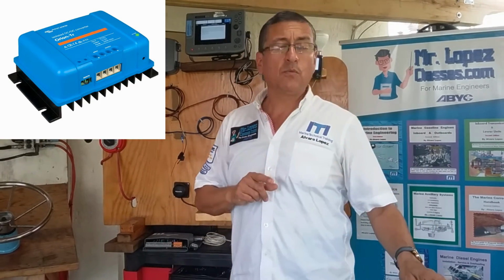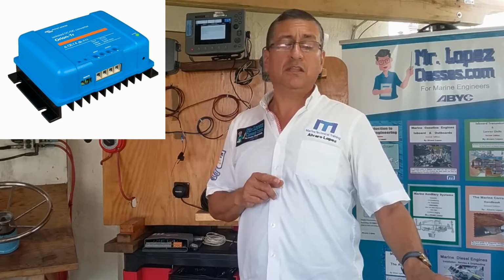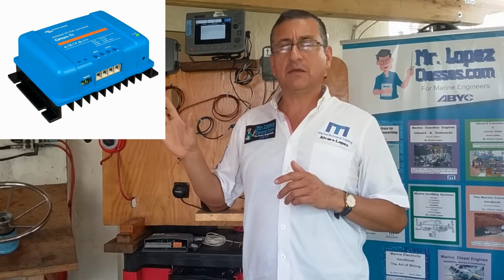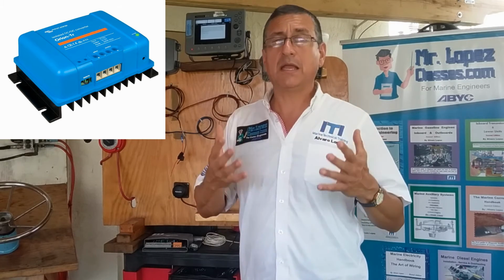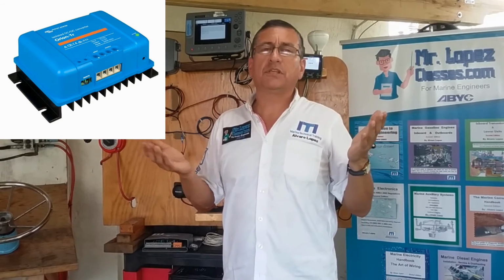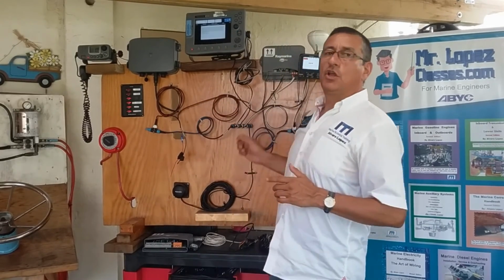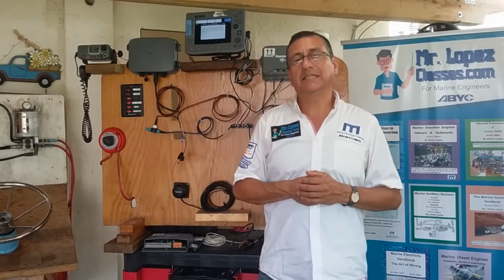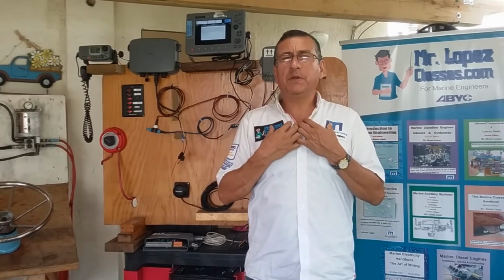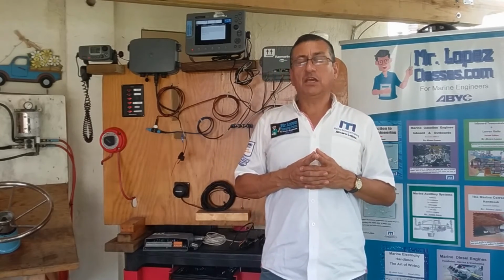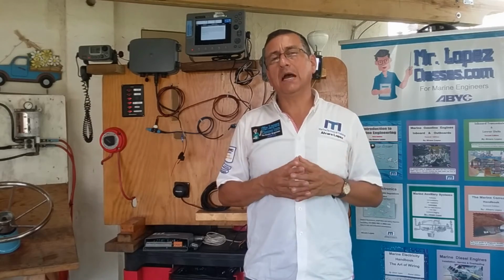All right. This is very, very important. There are other sources of power with the input coming from DC, and this is basically a regulator. Those sources of power, like the source of power that you have on the screen, are accepted and are highly recommended. Okay, that's your decision, depending on what you prefer. The most important part is, don't forget, my friends, in the backbone, no more than 8 amps. This is critical. This is in my opinion where the majority of the technicians make mistakes, introducing more than 8 amps.